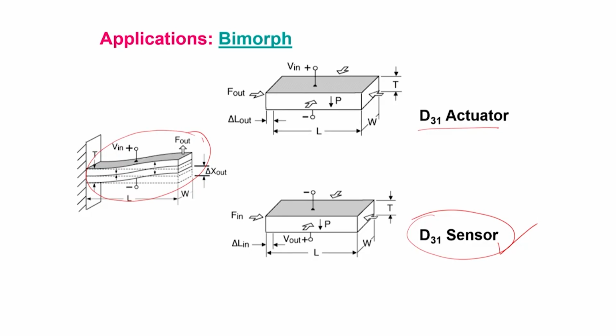So, if this piezoelectric material, as a bimorph attached with another passive material, vibrates this way or that way, that would create, in a time versus voltage plot, this vibration. This deflection that is happening here is going to create a voltage, and that is the voltage that can be used for sensing.